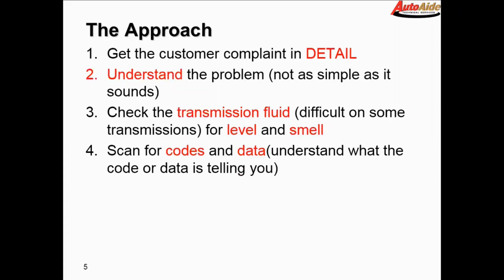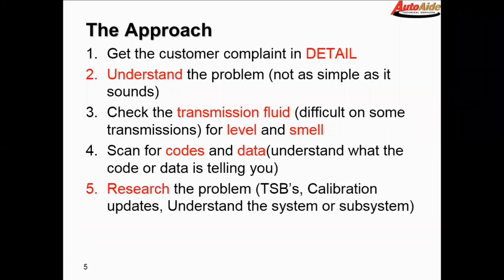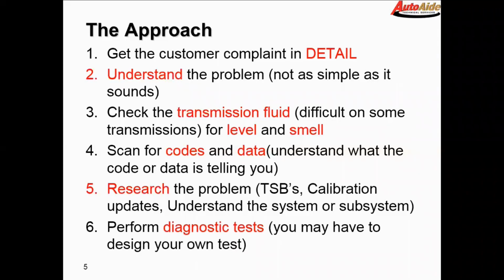And then you're going to get into it, scan it for codes, look at some data, try to get an understanding of what the codes or the data are telling you. And then you may want to do a little bit of research, check if there's any TSBs on your particular problem, calibration updates, that kind of stuff. And then perform your diagnostic tests.